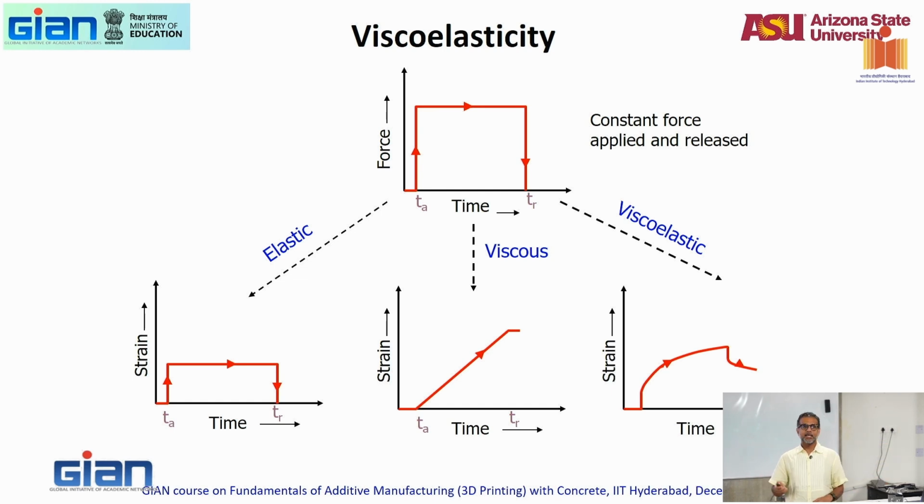If I take a viscoelastic material, instantly see what happens. The material thinks I am elastic. Instantly it thinks I'm elastic. It starts to behave the elastic way. Immediately some memory comes in and says, no, you're not elastic. You shouldn't be doing it. The viscous part picks up, and then that's what it is. And when you leave the force, same thing happens. Elasticity kicks in first. You have recovery of the elastic portion first, and then you will never recover your strain completely. Good. This is your viscoelastic material. So this is the idea of viscoelasticity.